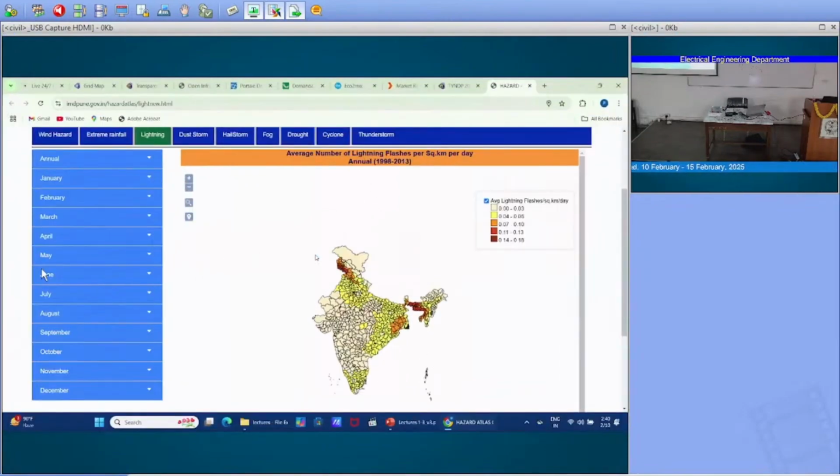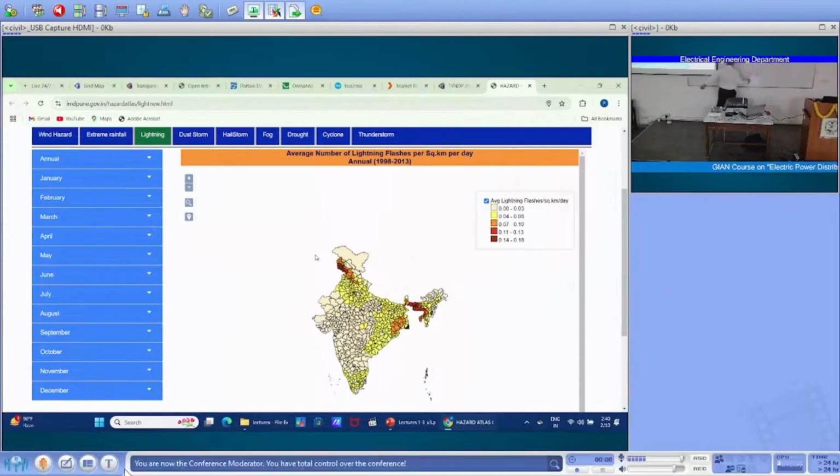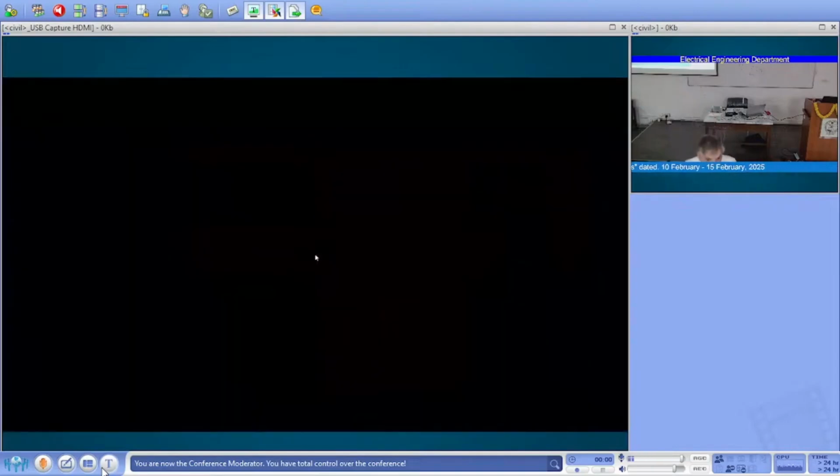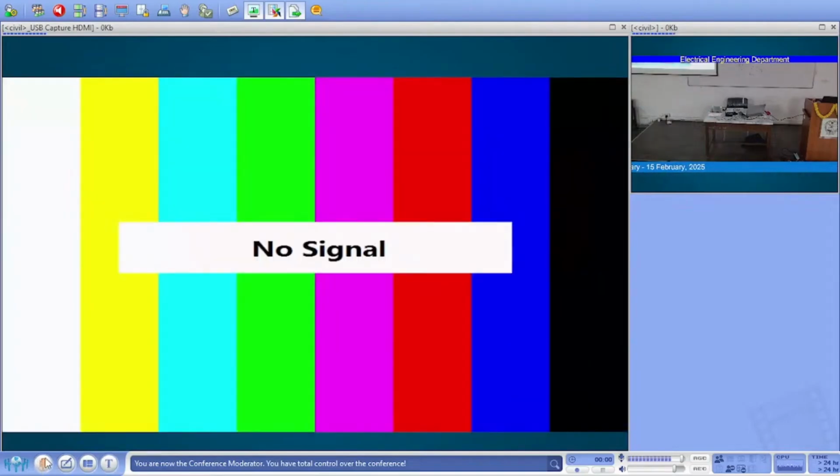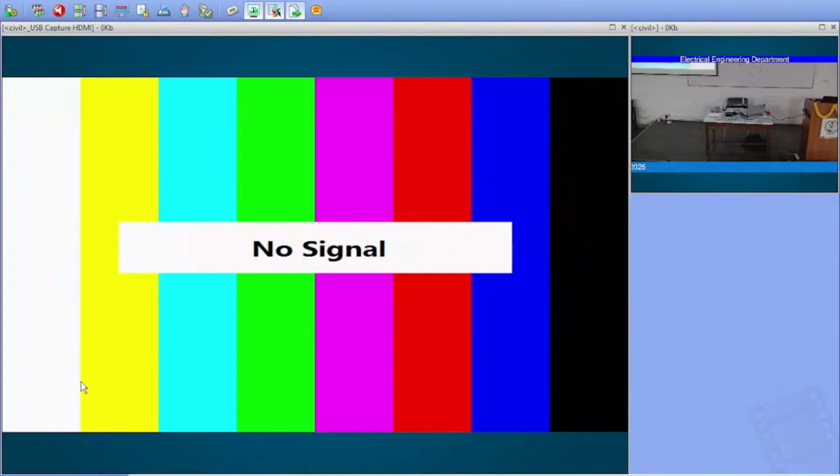And the typical front time for this lightning current, so the time to peak value, the time from 0 to the maximum, the median value is 3.3 microseconds. So you see, a very short and very fast pulse. No?